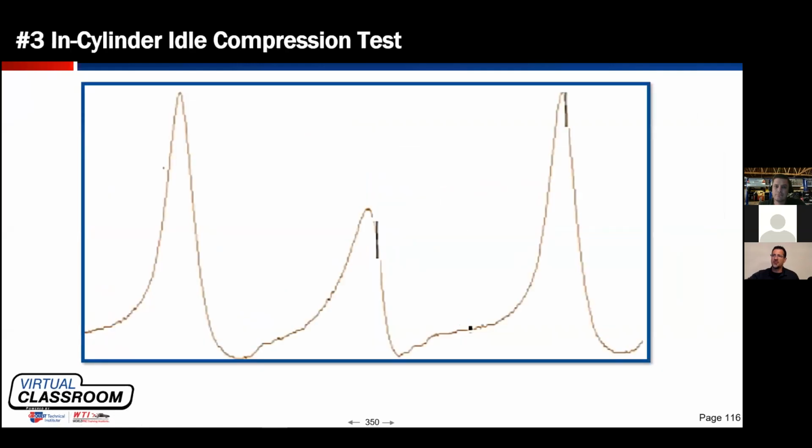So he goes in cylinder and he captures this. Now, I know there is nothing on this capture to designate what the pressure values are. And there is no overlay present to designate or infer cam or valve timing. But there's something on here that just is not quite right. What do you guys see on here as being strange?